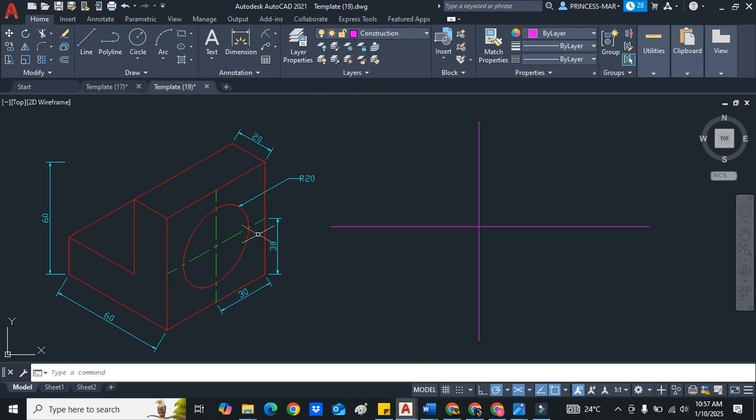So let's draw the circle first. The circle is radius 20. To draw a radius 20 circle, come in here by circle, we left click the down arrow, we click radius. We come over here by the center, left click the center, and we can pull the circle out.